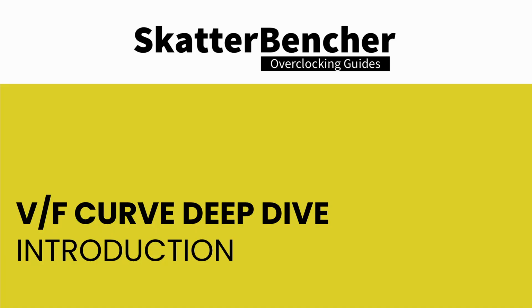But rarely I dig into how to figure out your maximum stable overclock. In this video, I want to do it a little bit different. So I want to cover how to find at least the baseline for your manual overclock by using the CPU VF curve. The VF curve, or voltage frequency curve, determines the relationship between the operating voltage and the operating frequency.